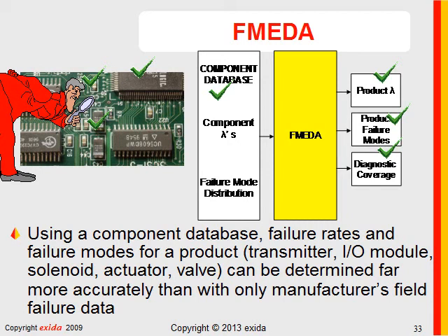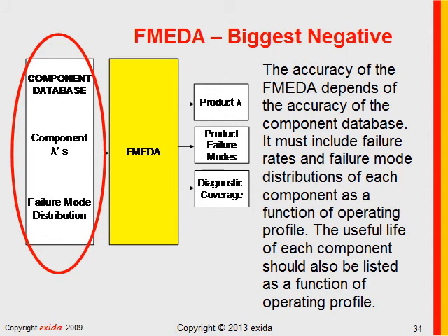And we think it's far more accurate than any manufacturer's field failure data. And few people would argue that one. But what's the problem? There is a big negative. The accuracy of the FMEDA depends on the accuracy of the component database, because it's garbage in, garbage out.